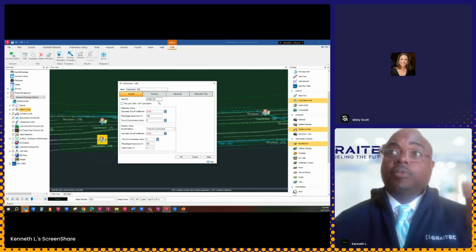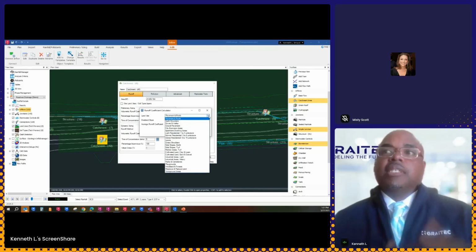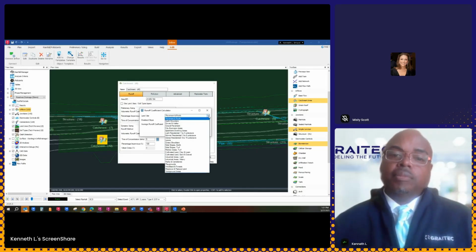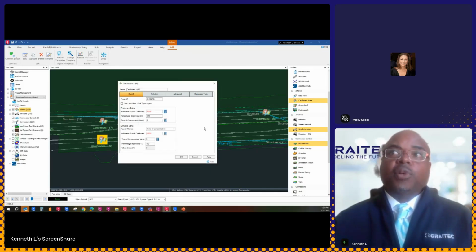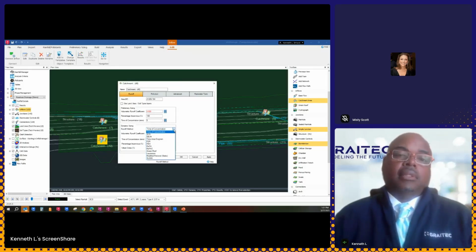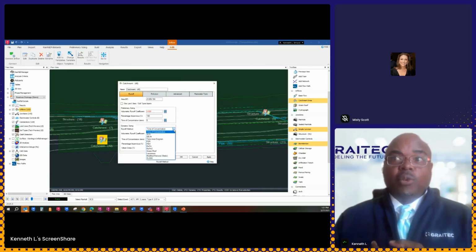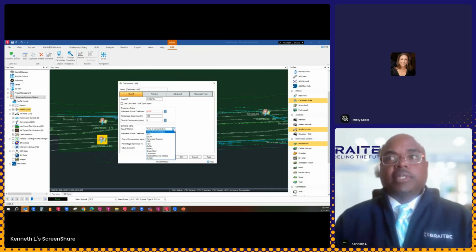You have a runoff with runoff coefficients and calculators with your catchment area. And if I just pick on this, it gives me options for my land usage. And then overland slope and flow slopes, pretty straightforward. But then also in terms of time of concentration. Now, clearly the SCS, green roof, SUDS, we have those options also.